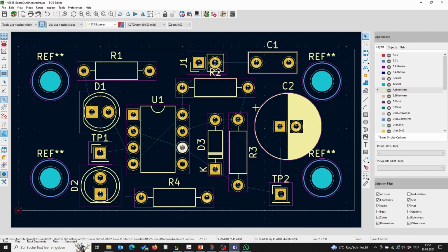And they should be at least inside of your board. So this one, C1, has to be moved, for example, to the bottom. Then we move maybe this to the right in order not to get confused. Honestly, the reference for the mounting holes we can delete. Select, delete, select, delete, select, delete.